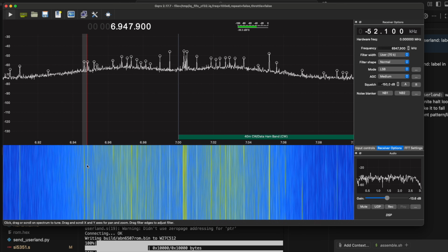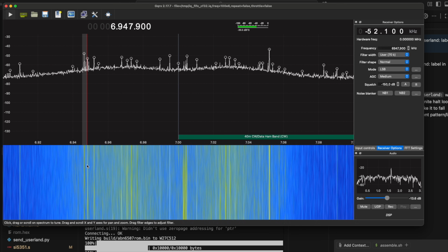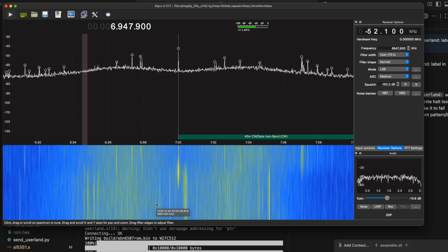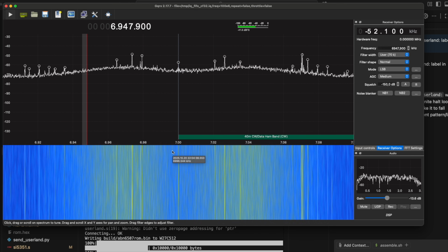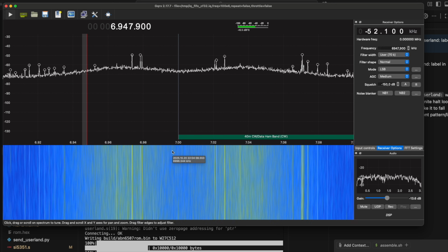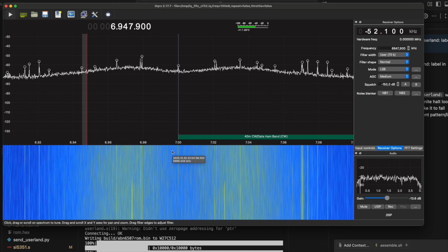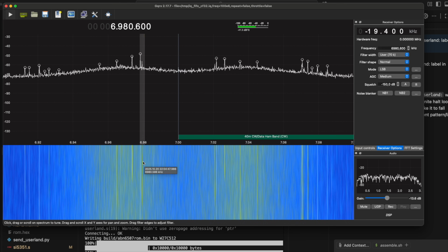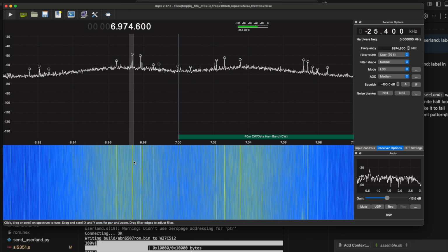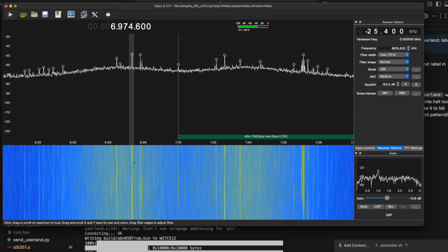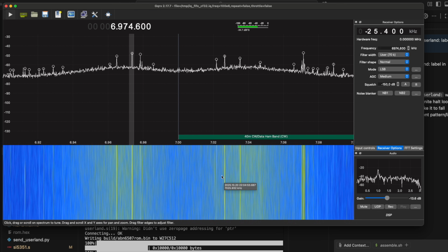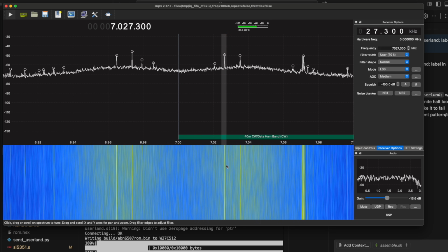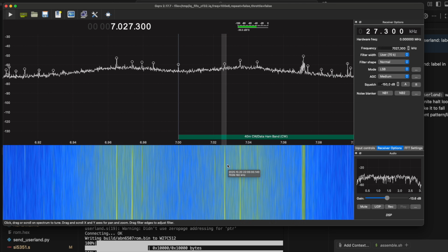Hooking it up to my 40-meter band antenna in the garage, I get a few AM stations, a bit of Morse code, and the usual clear squeal of FT8 coming through. But I also see a bit of aliasing, and the further away from center frequency we get, the worse image suppression gets. That's kind of to be expected, since we're not exactly using a high-end ADC, and any internal imbalance will cost mirror rejection. But something tells me we can improve the performance by increasing the gain on the PhaseLoom.